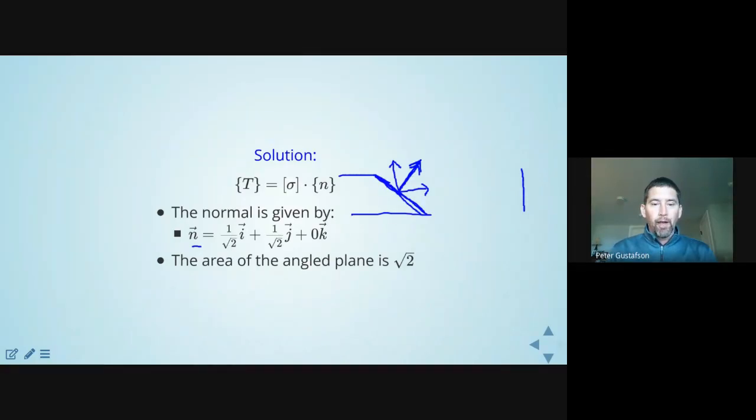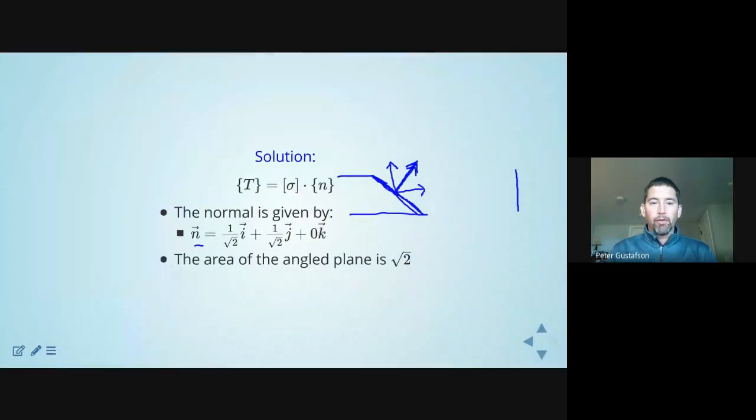These are the notes that we had from last time. We computed the normal component. We computed the shear component. We did it both for the very simplistic case where the new coordinate system was the original coordinate system. Of course, we found the same result as we had previously. Herein, we had the example where we're using this new coordinate system oriented 45 degrees to the other coordinate system. And we were able to calculate with that system also the normal and shear components.